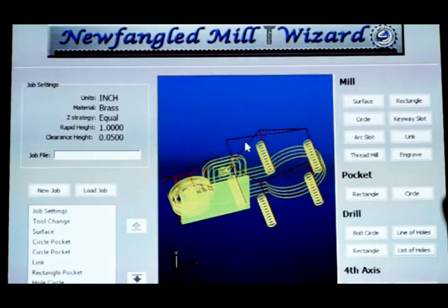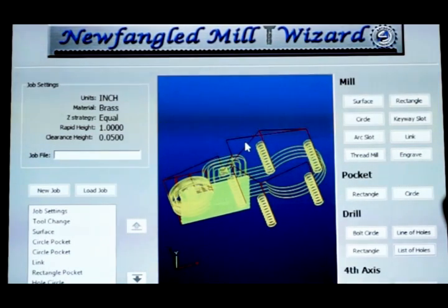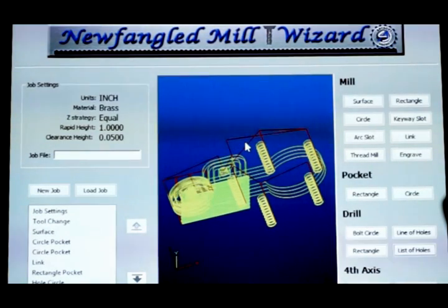So that's what we do with all of the drilling cycle things. All of them work with the same structure. You notice things that look alike, that's because I want to keep the code alike in all of them. So the right-hand side of all of the screens does basically the same thing in every case. The left-hand side calculates the direction where the next hole is going to be. For fourth axis, I do the gear cutting and the spline cutting only because my rule was if it was in the original Mach4 Wizards, I need it here. Okay? So those are there.